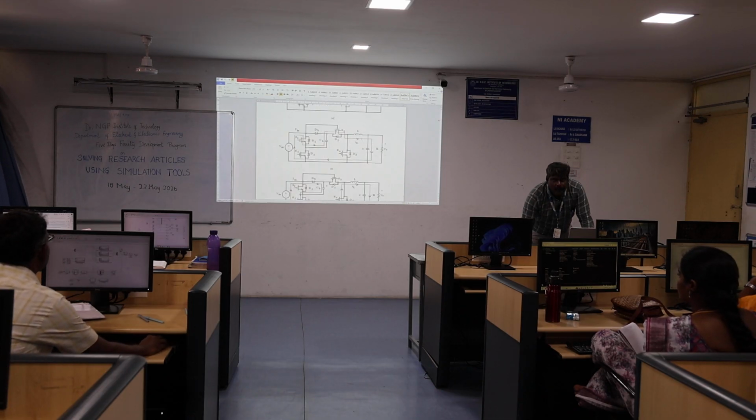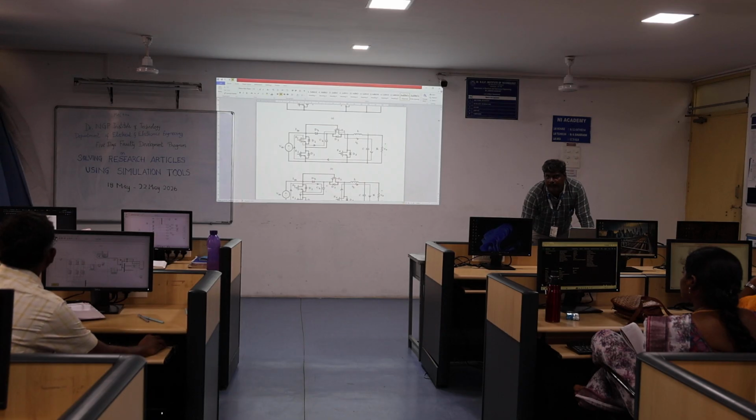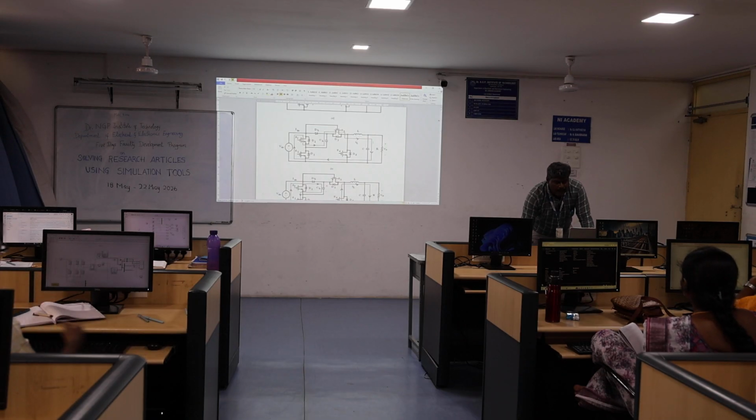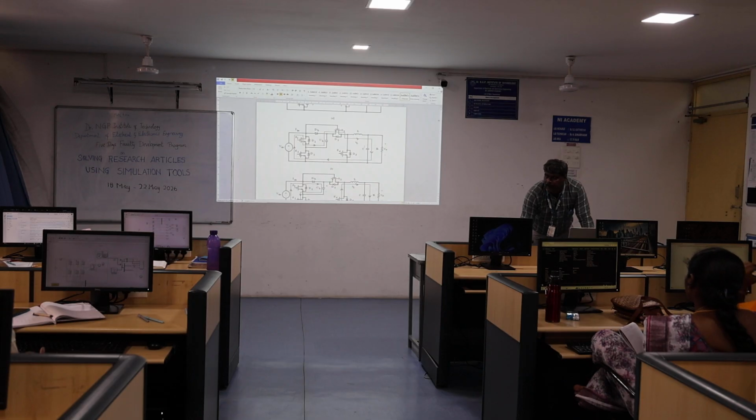Next, we have to write down the current through the inductor formula. So current through the inductor is IL. Here you have a node. Now in this node we are going to apply Kirchhoff's current law. So the current entering the node is the inductor current IL. Then the currents leaving the node are the capacitor current IC and I0. I0 can be written as V0 by R. Then the current through the capacitor we represent as C into dVC by dt. This is the formula for the current through the capacitor, because we need to find the derivative of the state variable.